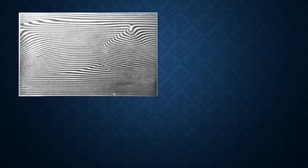Next, this is the interferometry model, the flow visualization interferogram, which has been obtained at Mach number 1.61. At Mach number 1.61, this is nothing but a nozzle, right? At the nozzle exit, we are having Mach number 1.61.